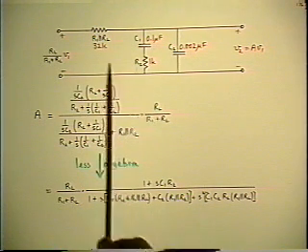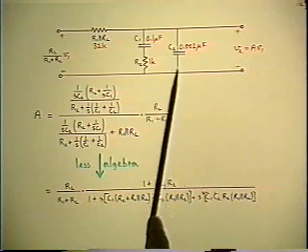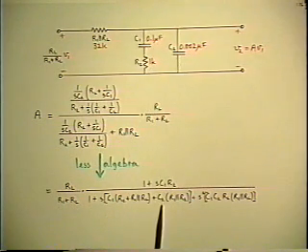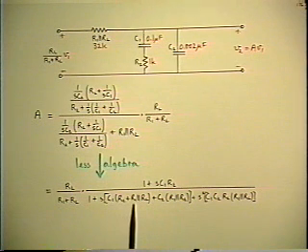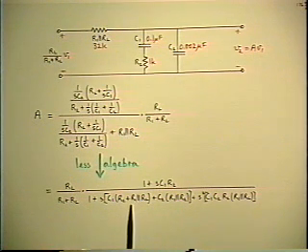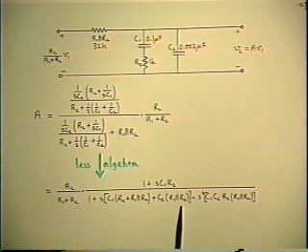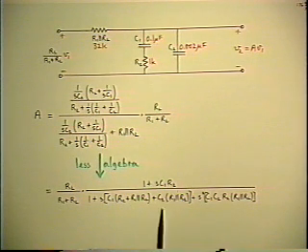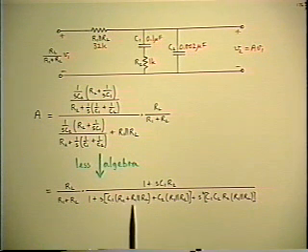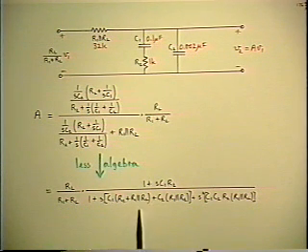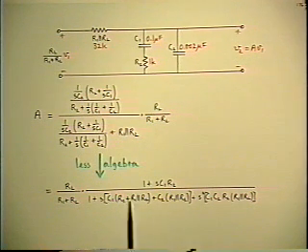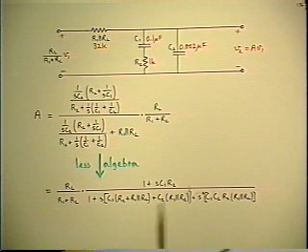And when you look at the tentative set of values, you see that the C1 is 50 times bigger than C2. And associated with the C1 is a resistance which is bigger than the resistance associated with C2. So both of those effects go in the same direction to make the C1 term even more than 50 times bigger than the C2 term.